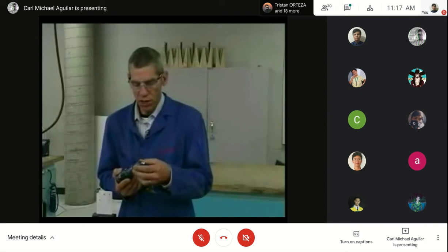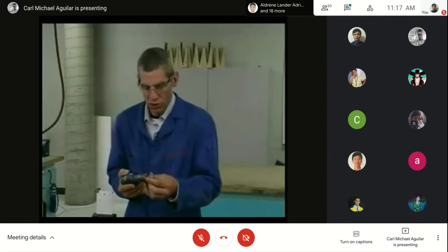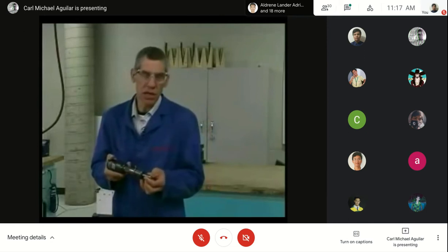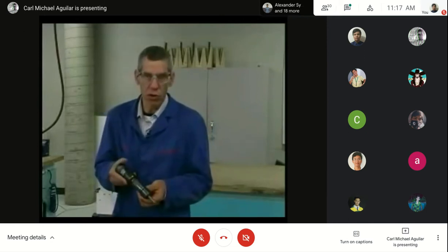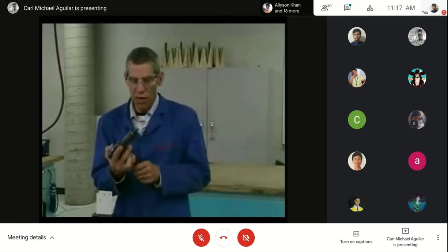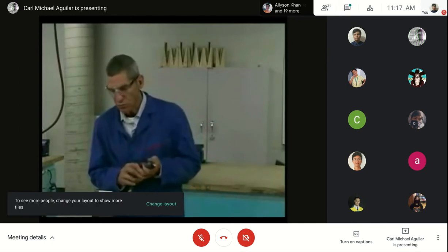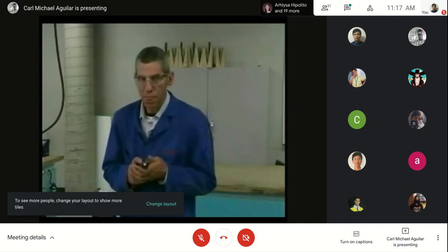Install the beehive or the safety spring onto the gun. Don't tighten it too tight, just a few turns is all that's needed. It'll stop the rivet set from falling out when you're handling it, and it'll stop it from becoming a projectile if you accidentally hit the trigger while the air is plugged in. That's an important safety step.